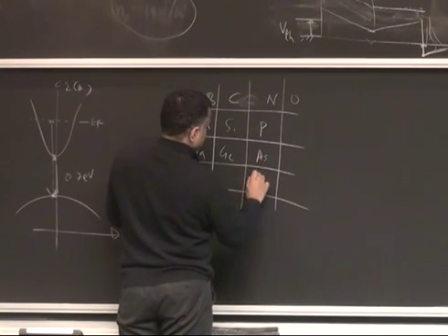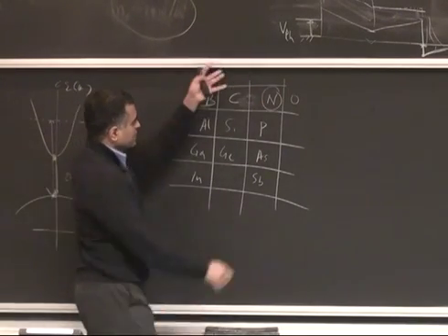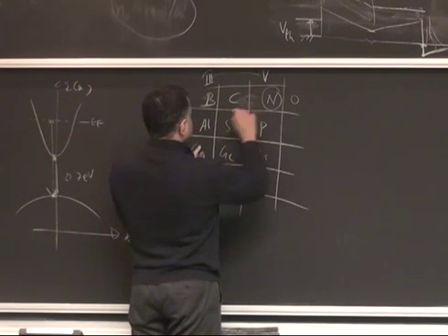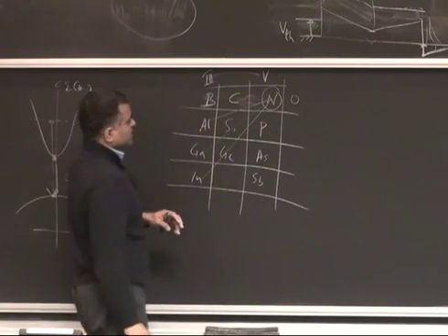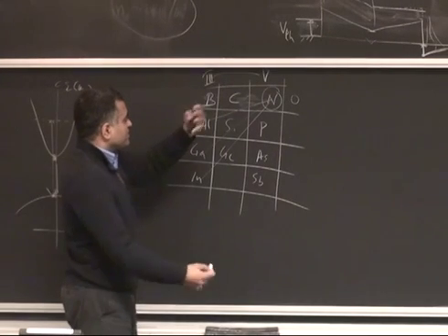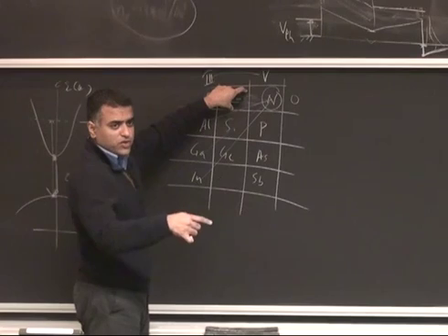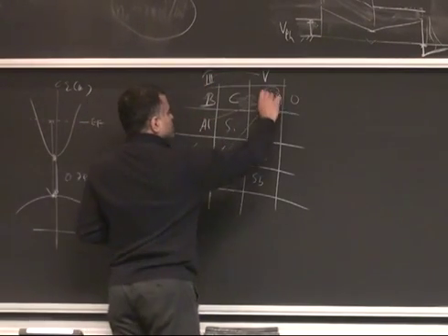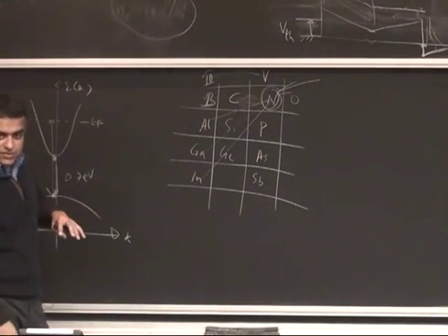Phosphorus, arsenic, antimony, right? So nitrogen is sitting right on the top of group 5. This is group 5, group 3, and we're looking at the III-V semiconductors: gallium nitride, aluminum nitride, indium nitride. And very soon there is going to be quite a bit of interest in looking at boron nitride as a compound semiconductor counterpart of carbon or diamond in 3D. We already talked about 2D boron nitride in the beginning, but I'm talking about 3D boron nitride. Anyway, right now, nitrogen is the lightest group 5 element, and it's also the most electronegative among all.